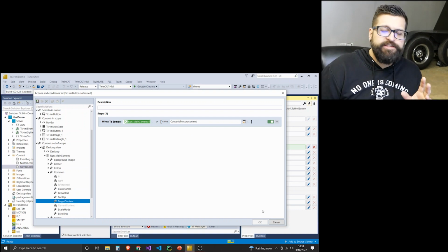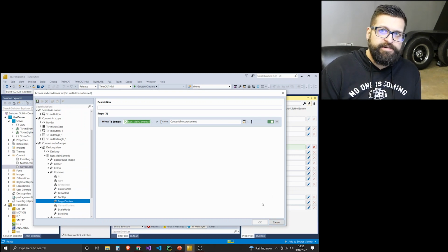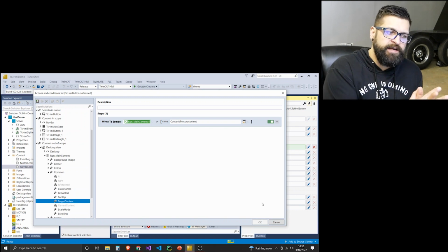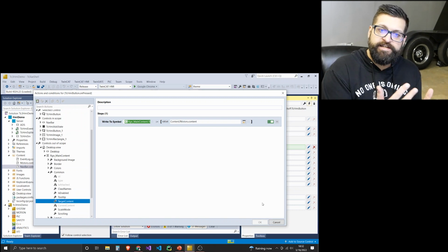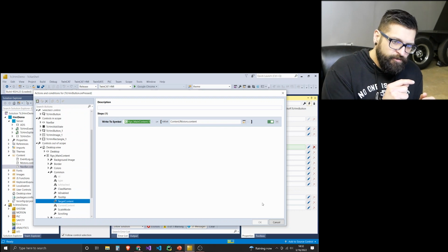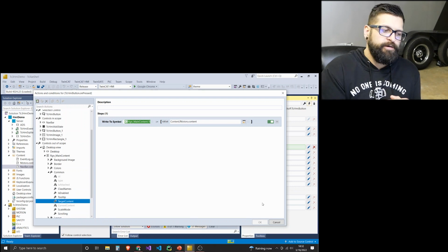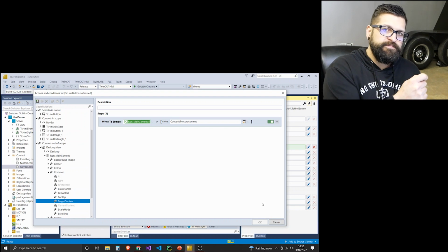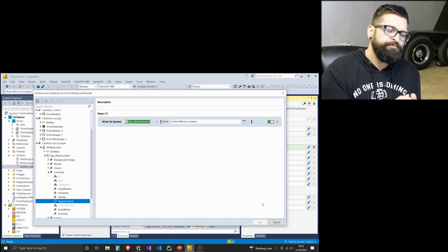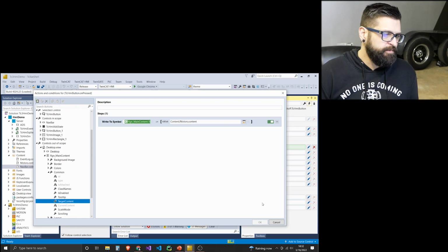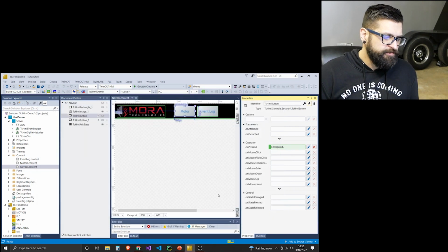And that's just repeated throughout here is how we use event listeners to trigger events that are dynamically changing properties in our controls. That's the primary task that we're doing when we're changing the HMI. And then the corollary to that is when we're changing the value of symbols in the PLC, we're triggering events that are writing to mapped symbols in the web server that are tied to a symbol in the PLC. So that's basically the approach that we're going with, or at least that I went with. I'm sure there's smarter people that have much better control schemes than that.